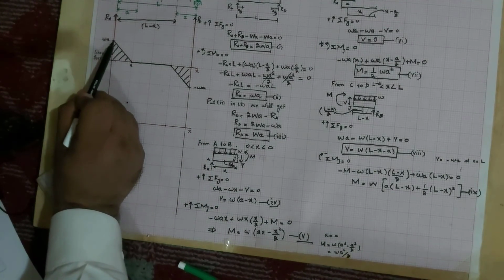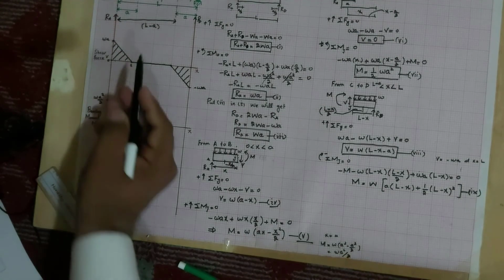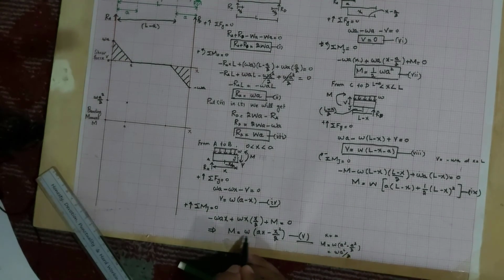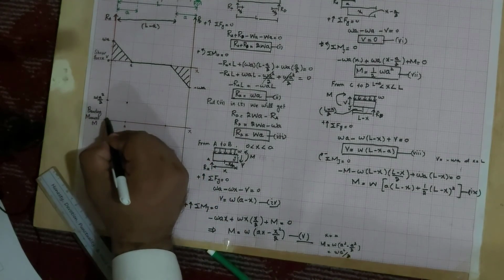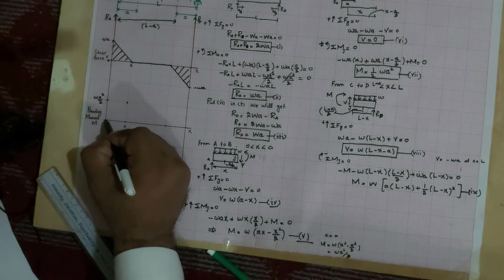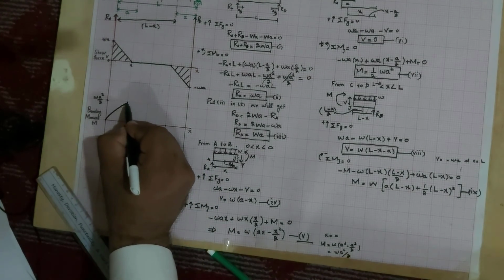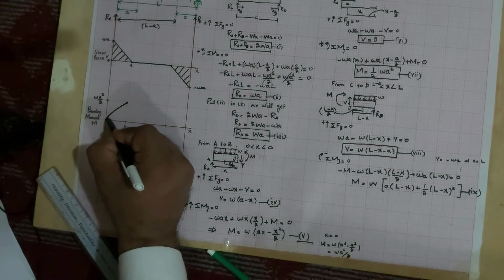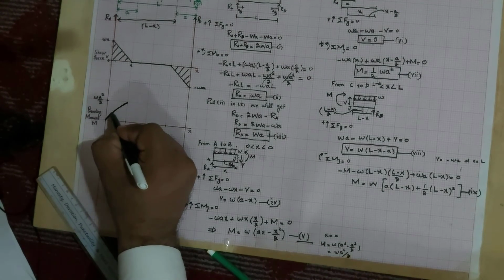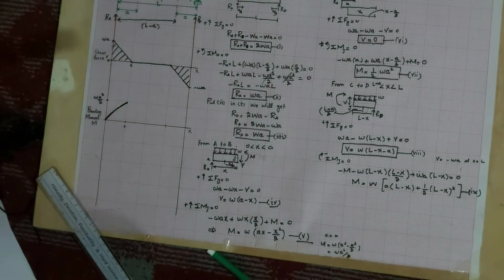The shear force is a linear equation, and you can see that the bending moment equation is a second-degree equation. So it will not be straight. Instead, it will be like a curve, and it can be found accurately if you have the proper x and different values available.